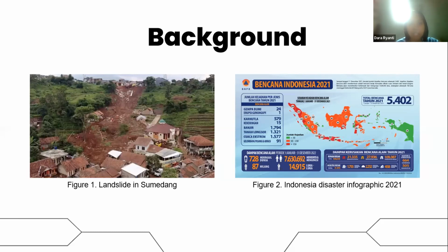Landslides can be caused by several reasons, including human and natural factors. One of the natural factors that influence landslides are the soil layer, slip surface, and saturated soil. The slip surface is a water-resistant and slippery area which generally consists of a clay layer. The resistivity geoelectric method can produce an image of the subsurface rock layer based on the resistivity value of the rock type that constitutes the layer, which is estimated to be the cause of landslides.